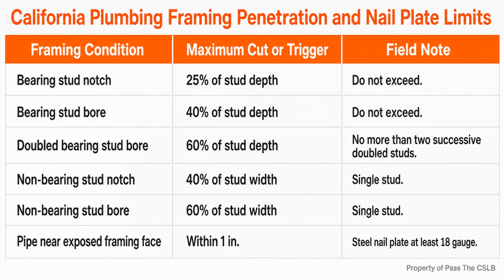I look for a proper trap with a continuous seal and a vented horizontal connection rather than an S-trap. I verify the vent route to the roof and check its relationship to openings and air intakes. I confirm the horizontal pipe size, uniform slope, support, and route. Then I find the cleanouts. I check the upper terminal, long-run spacing, accumulated changes in direction, and the clear working space in front of each access point. I look at lower-level fixtures and compare their elevation with the next upstream manhole cover when a backwater condition may exist.